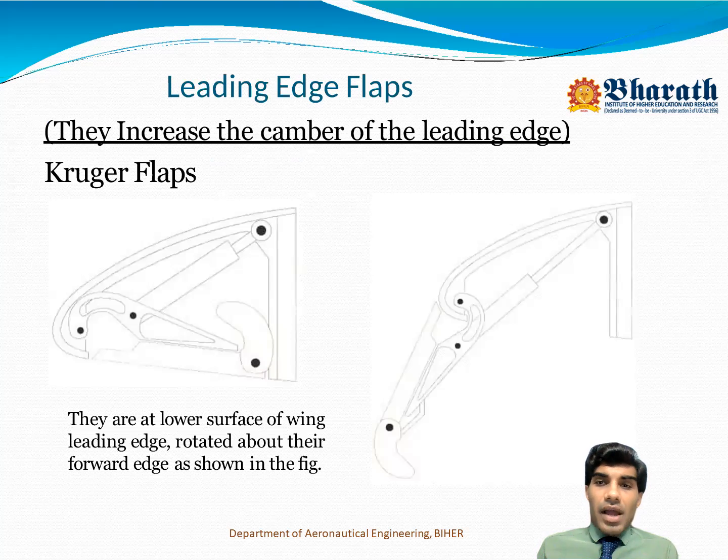So leading edge flaps. What exactly are leading edge flaps doing? They increase the camber of the leading edge. So these are on the leading edge, and they increase the camber of the leading edge, which will increase the coefficient of lift, which will increase the lift of the wing.